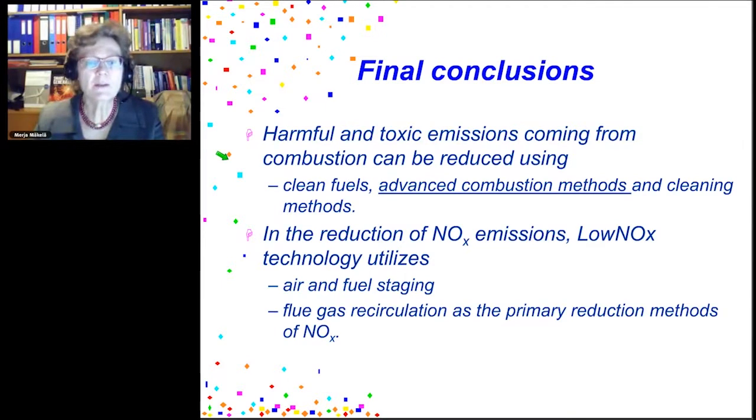In these presentations, I have discussed the reduction of nitrogen emissions using LowNOx technologies. The main principles in LowNOx technologies are air and fuel staging, and also the flue gas recirculation, and these methods are called primary reduction methods of nitrogen oxides.